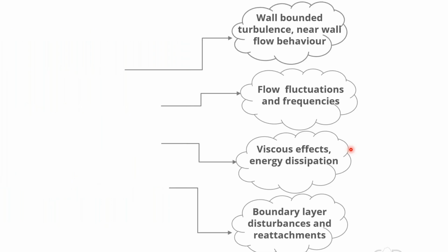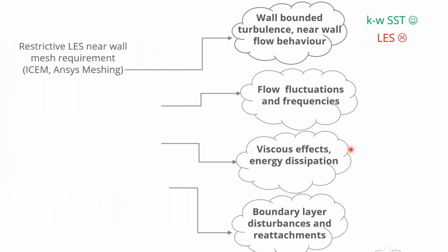So have a look through this. As with the wall-bounded turbulence model, David has already described the significant challenges in producing the required mesh. So in terms of the LES, it's quite stringent and quite restrictive, but the RANS model, such as the k-omega SST, is not so bad when we think about resolving the turbulence with a RANS mesh.